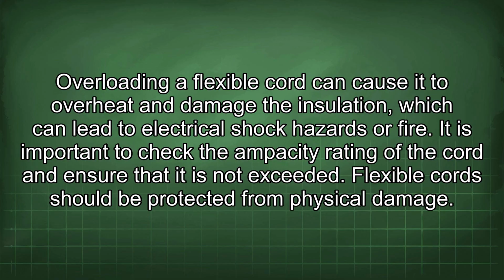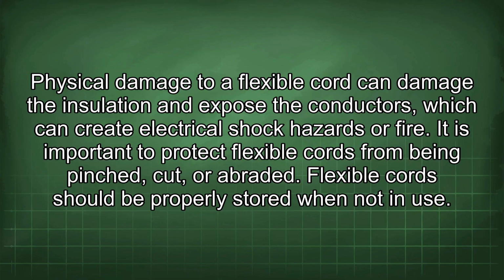Flexible cords should be protected from physical damage. Physical damage to a flexible cord can damage the insulation and expose the conductors, which can create electrical shock hazards or fire. It is important to protect flexible cords from being pinched, cut, or abraded.